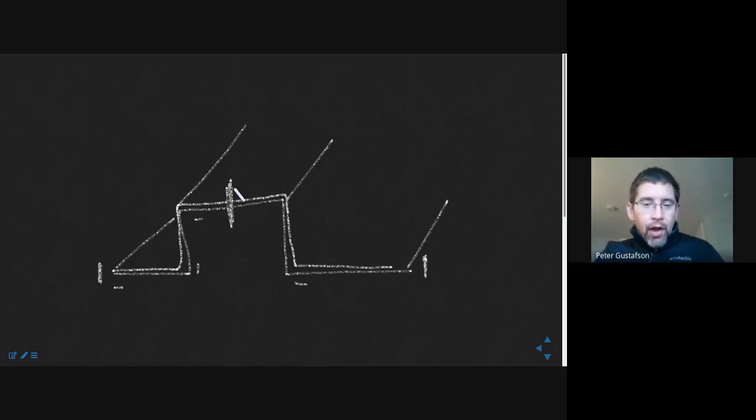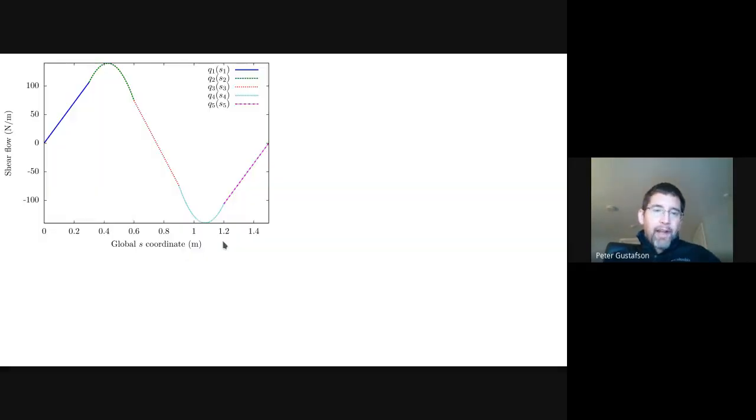In this case, that symmetry is actually anti-symmetry, so it's going to be anti-symmetric relative to that symmetry plane. So you can see it's positive shear flow on the left side, goes back through zero at the midpoint, because in order to be anti-symmetric it has to cross zero at that symmetric plane, becomes negative as we go further down, and then eventually comes back to be zero.